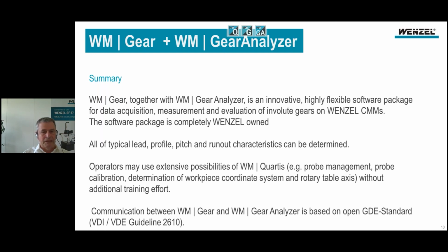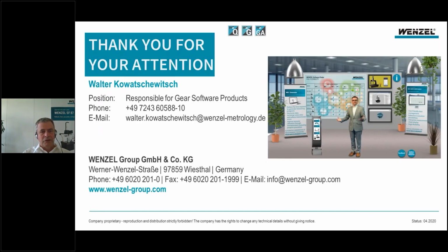And all of the typical lead, profile, pitch, and run-out characteristics can be determined, and the operators may use the extensive possibilities of Quartis, for example, for the probe management, calibration, workpiece coordinate system determination, rotary table system without additional training effort. And the communication between the gear and the gear analyzer is based on the open GDE standard VDI VDE Guideline 2610.